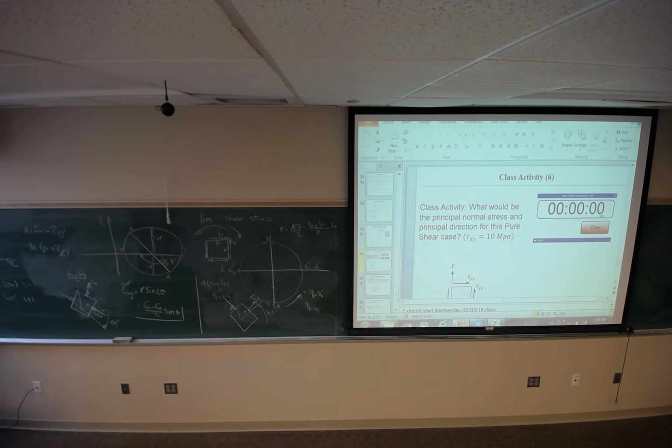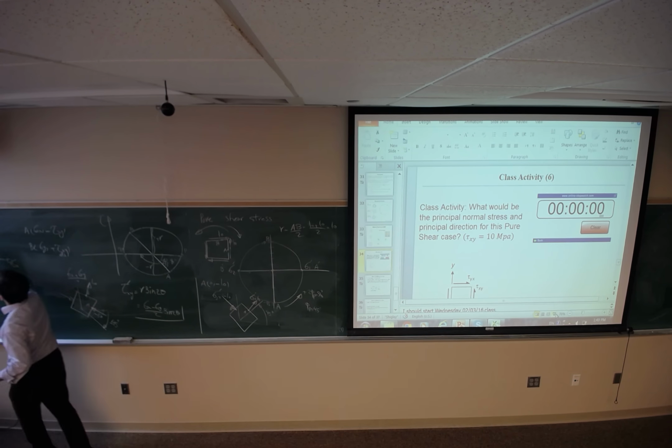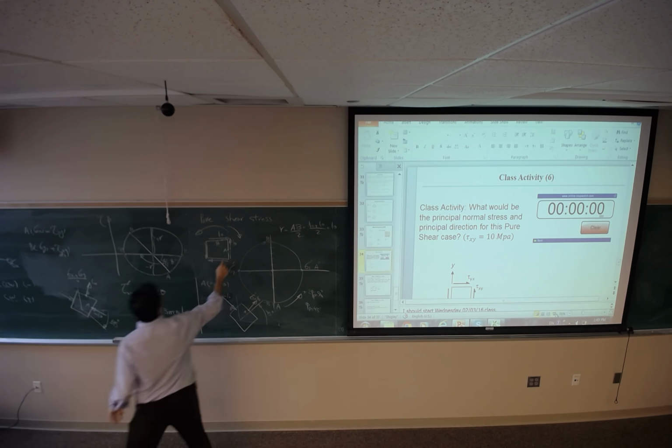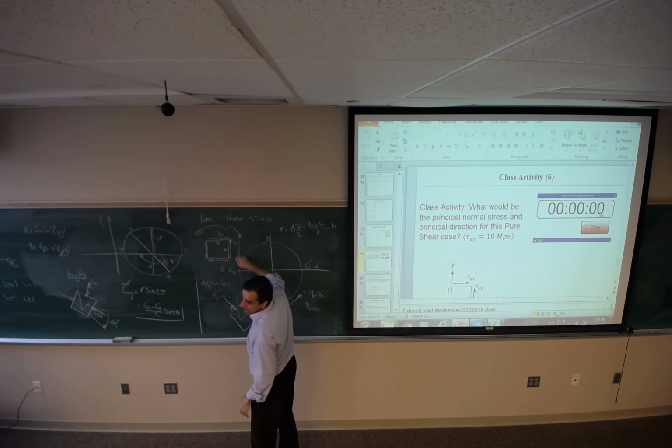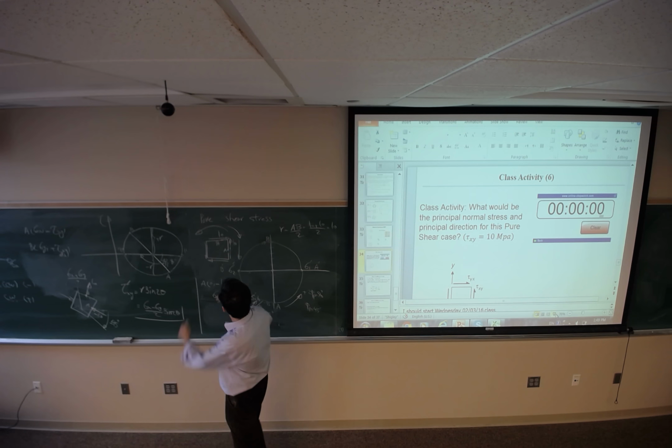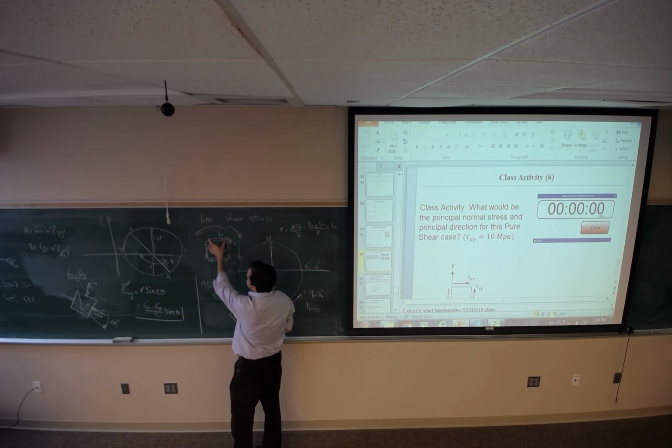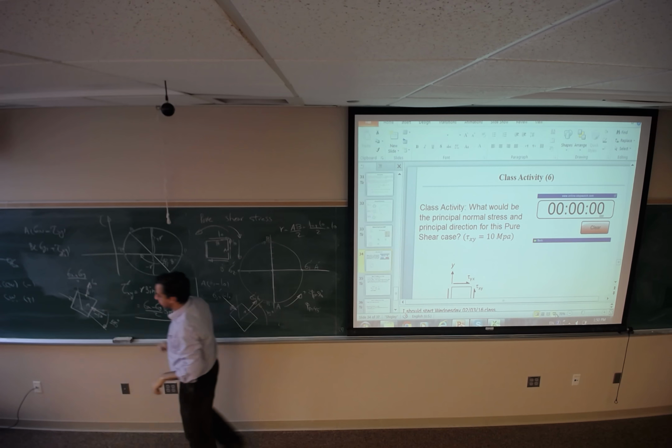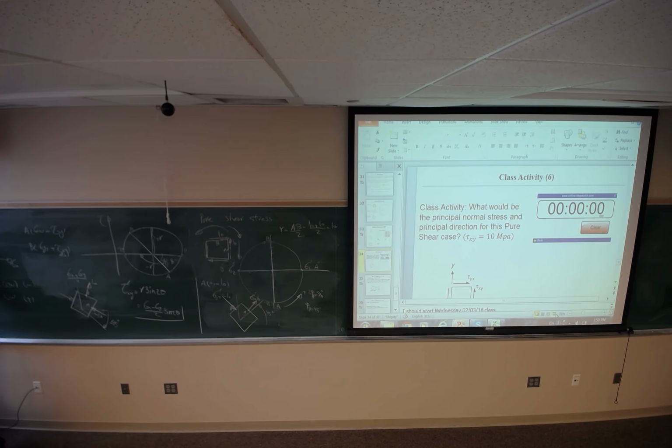Yep. If I say the shear stress is -10, it tells you it should be clockwise on the right plane. So just draw a shear stress pointing down to make it clockwise. And then after you figure this out, you can find the other arrows' directions. It goes in the opposite direction: it goes up, and it goes to the left. Okay, so everything goes back to the right side. Good question.